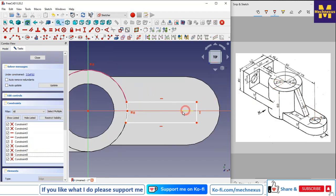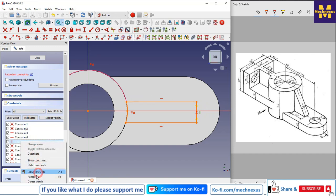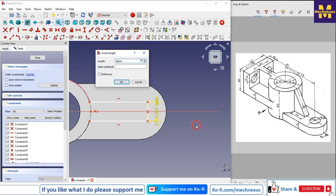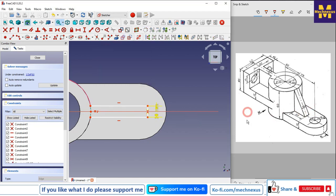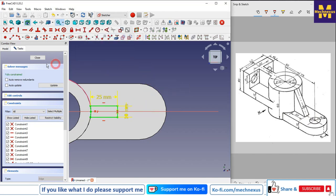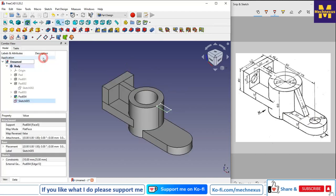And this is also 10 mm, so I will use the symmetricity option. I will select this point and this axis, and I will delete this, and I will give my dimension 10 mm, and this is a 25, so I will select this and give the horizontal dimension 25, and I will close it.